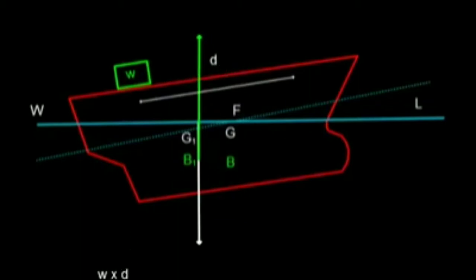Well, this weight is shifted from forward to aft with the distance d. So we can say the shift in the center of gravity of the ship is GG1, and that is in this direction, G to G1, and it is going to be small w into d divided by capital W, where small w is this weight and d is the distance shifted.